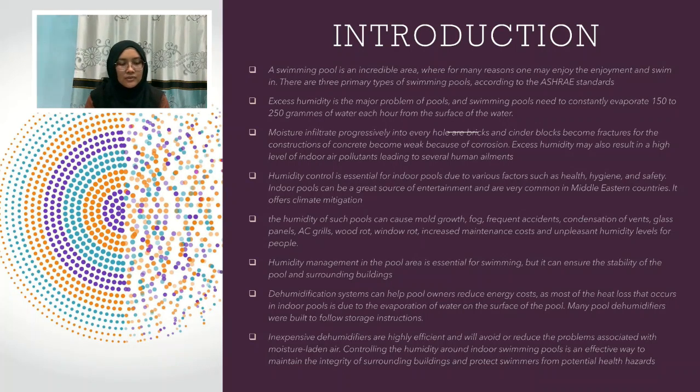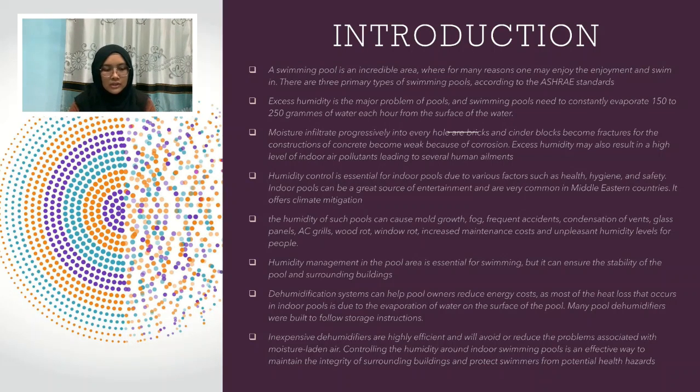Moisture infiltrates progressively into every hole. Brick and cinder blocks become fractured, and the concrete of the construction becomes weak because of corrosion. Excess humidity may also result in a high level of indoor air pollution, leading to severe human ailments. Humidity control is essential for an indoor pool due to various factors such as health, hygiene, and safety.